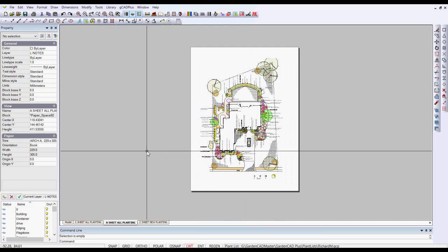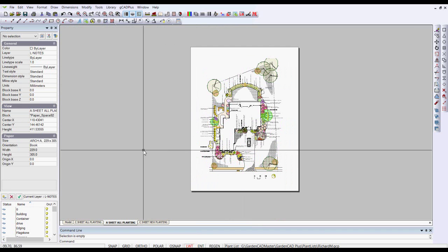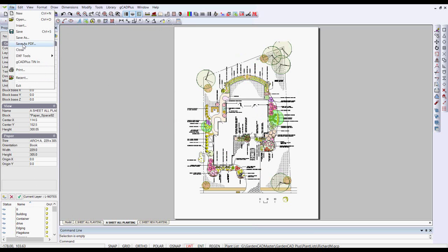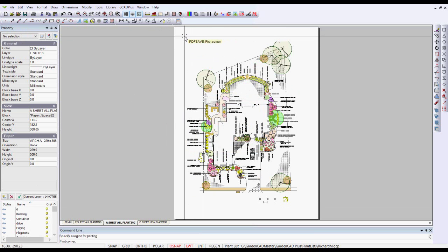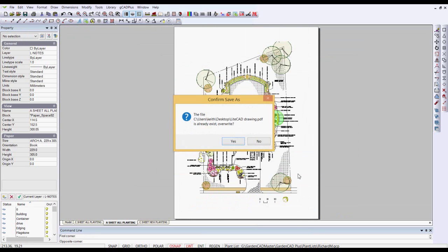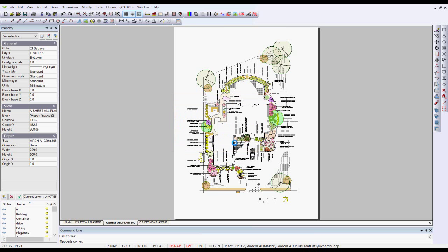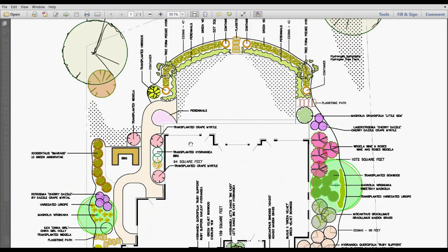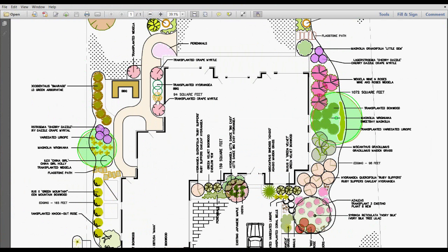Now, sorry about that, we had to do a little bit of extra work, but we're on an A size sheet, a much smaller sheet. And now we're going to zoom extents and save to PDF again. Now remember, we had exactly the same settings as we had first on the C size sheet. So it's File, Save as PDF, put our box around our design, and what I'm hoping to see is we'll have a whole series of very thick lines now, because same line weight settings. Let me maximize that, and can you see we now have very, very heavy lines, not only around the barbecue but right the way through the drawing.